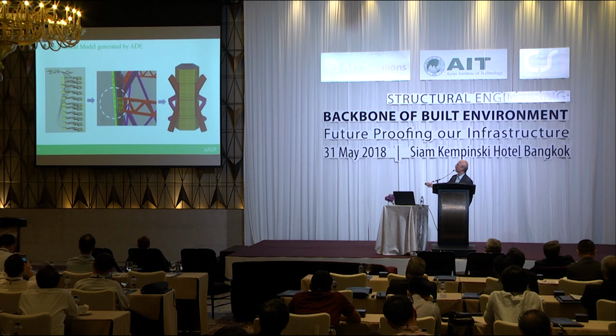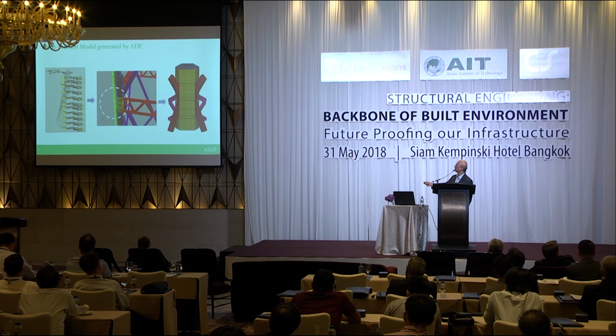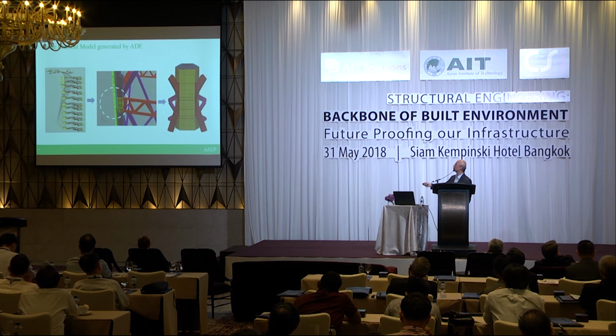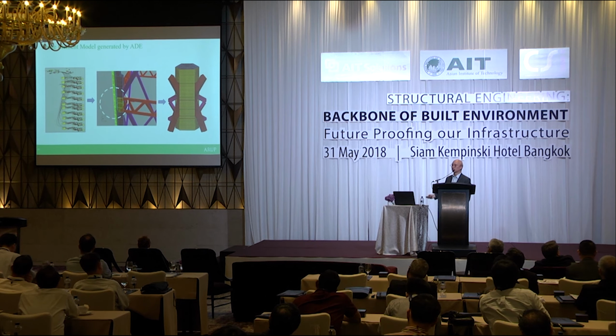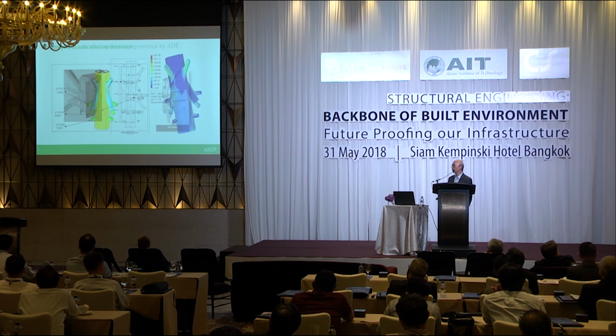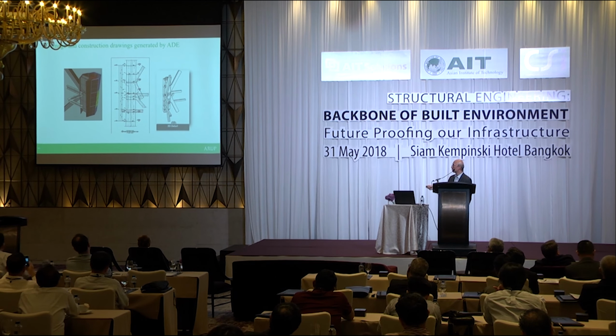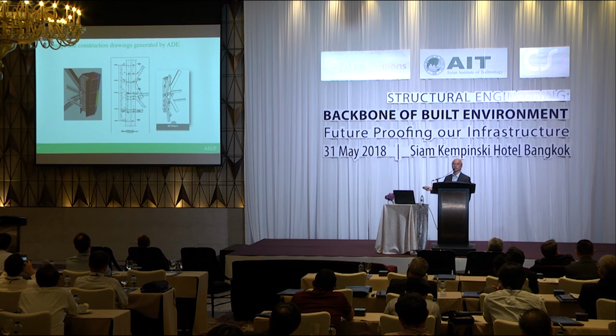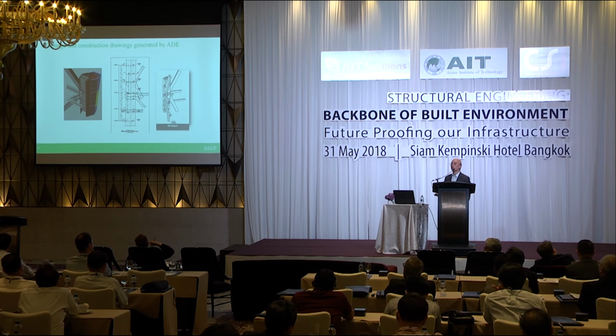Again, this one is how we make the computer model. And actually, this is based on the global model. And then we extract this part and do the meshing. And then based on this, we can do the finite element analysis for the connections, right? For detail analysis for the connection. And then we can check the stress and also check the strain. Again, based on this one, we can do all the shop drawings. And then the contractor can, based on this, do the connections.